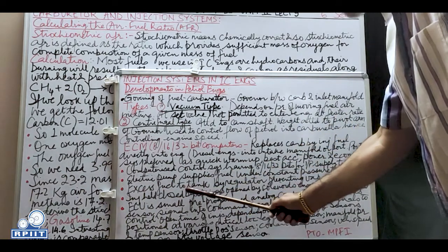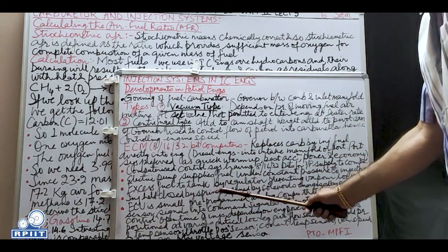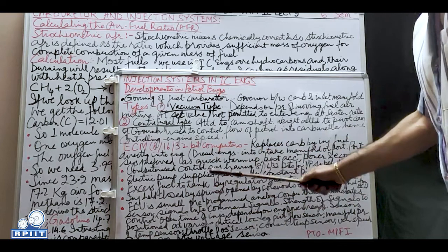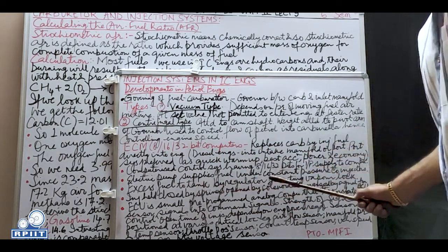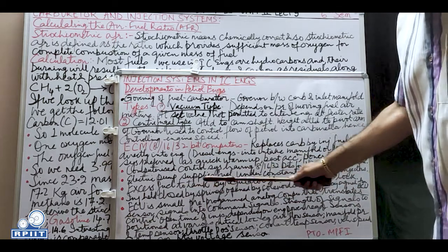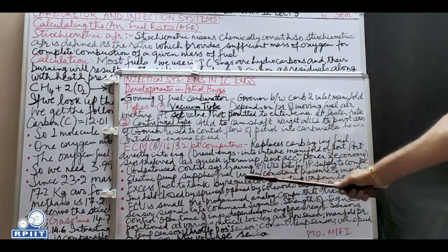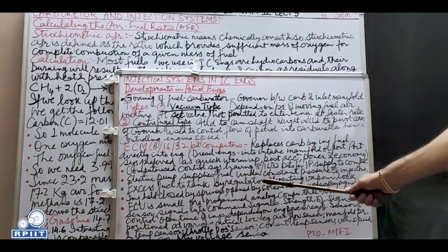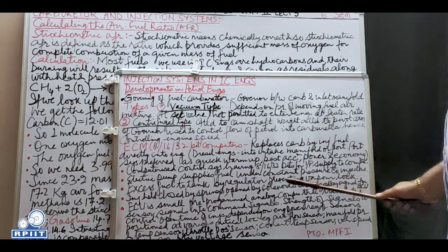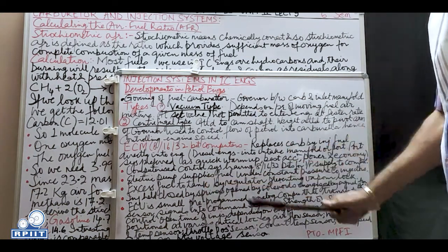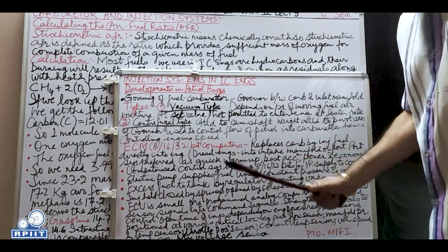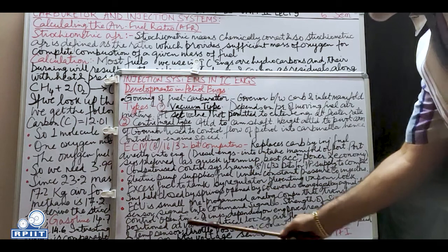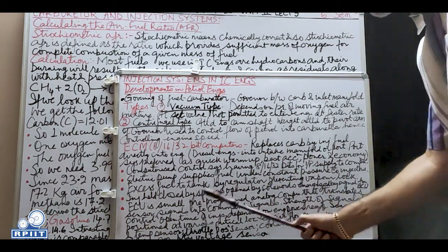Excess fuel goes back to the tank through the bypass valve. Whatever fuel is required by the injector, the rest it rejects, and we can't waste the fuel. It goes back by the regulator, preventing vapor lock. Otherwise, if it continues staying, vapor lock may occur. Excess fuel is sent back to the fuel tank by the regulator, preventing vapor lock.